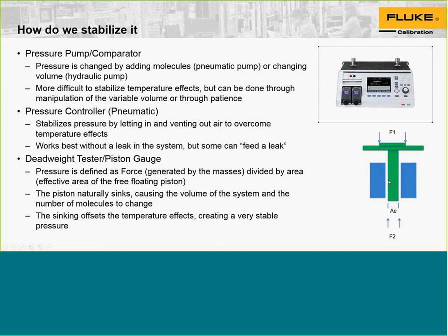As the piston is floating, fluid will traverse between the piston and the cylinder. So it will escape between the piston and the cylinder. This is somewhat different from what we normally think of in a system, because while the media is leaking out of the system between there, if the annulus is too large in a liquid system, you could actually have a puddle of oil forming at the base of your tester.